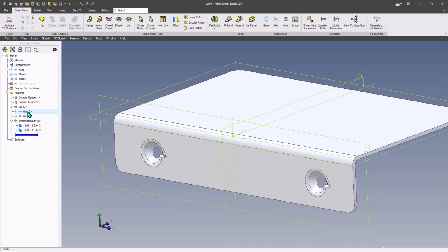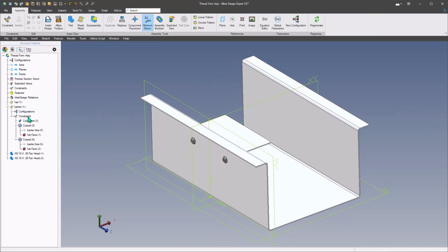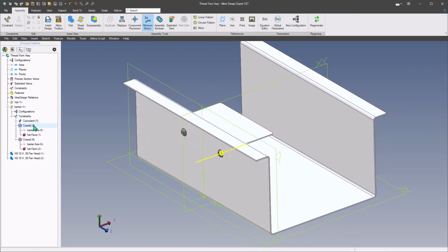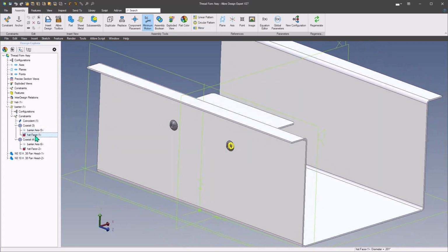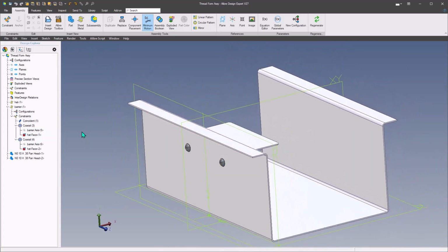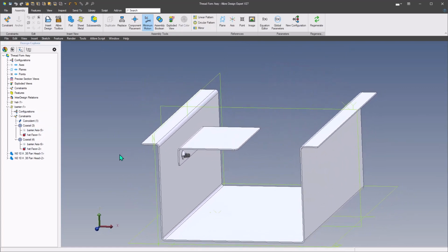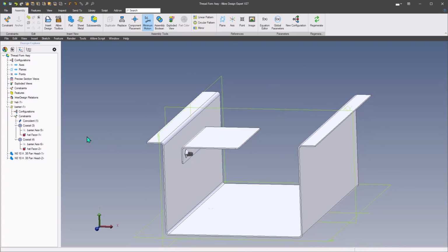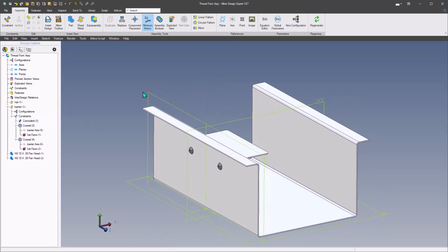One other thing that you want to do is on your pre-punch, add some axes to each one. That's going to help you when you insert this part into another sheet metal component or mate it with another part. Like in this assembly, you can see that it's constraining the axis on the barrier to the face of the hole in this hat section, and on both holes that gives you the coaxial condition for mating this barrier onto the surface of this, as far as lining up with the holes. And then there's also the coincident, of course, that gives you the face-to-face coincidence.